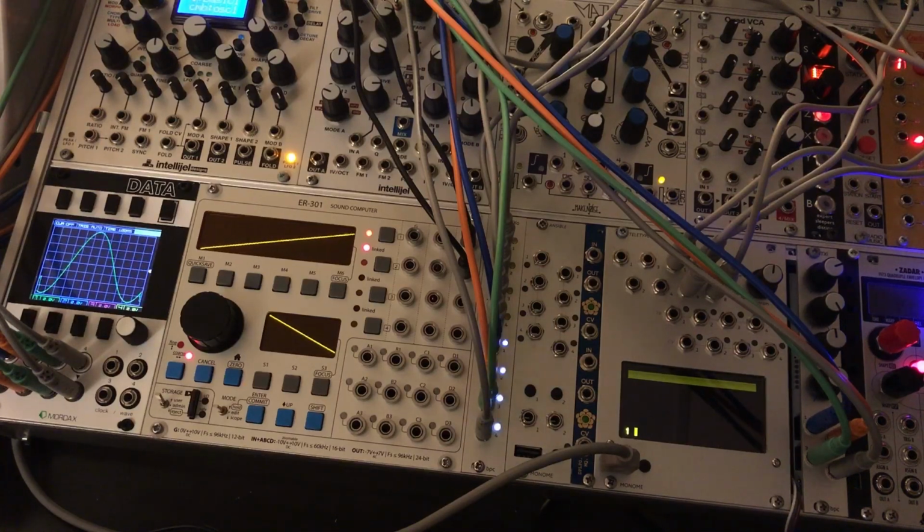And what we want to do is set the phase of each of these 90 degrees out of phase. Actually, let me jump back over to the command screen here, and let's just do divide. I think it was 16,383, and let's divide that by 4, and we get 4095. So basically, we want to add an offset of 4095 to each of these.